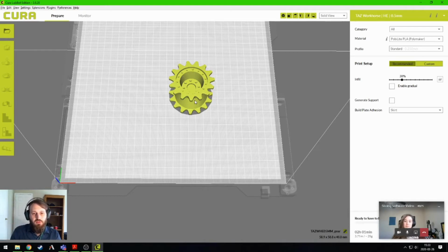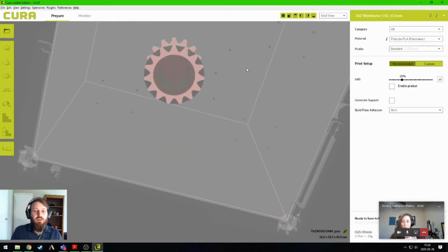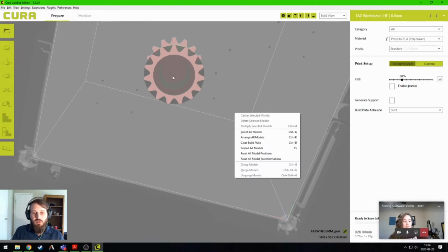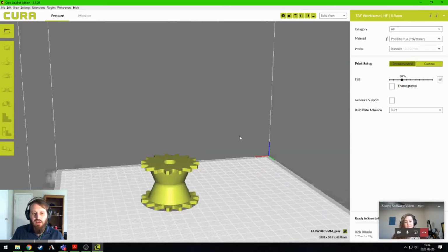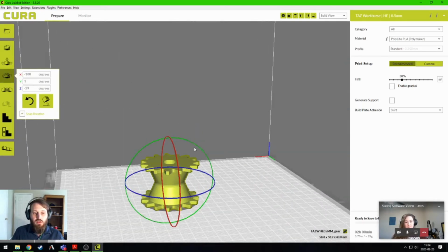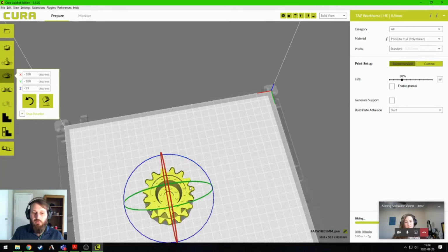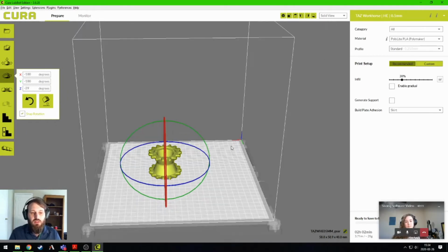But if I flip this around, whenever you have a support structure or a structure like this with an opening like Alex was talking about here, you don't want to have to build supports in this. So finding the flattest part of the object would help. With this one being flat on the top, I then rotate that to be the bottom, and now it can build out that a lot better because that empty space is going to be built up as it goes layer by layer instead of having to do scaffolding bit by bit. So flattest part if possible, and rotate can help you get that.